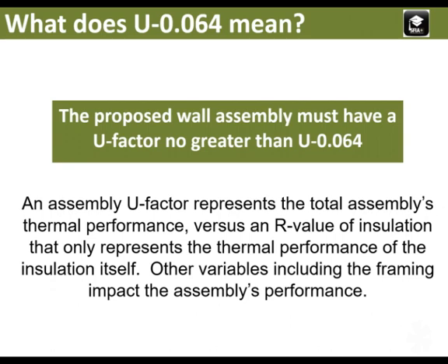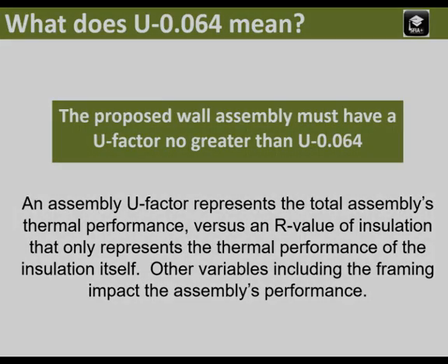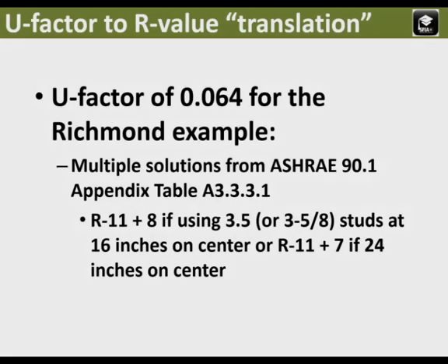Remember that this is different from the R value that only reflects the performance of the insulation versus the entire assembly. One point of clarification here is that you might see or hear someone talking about the effective R value of a wall. If that's the case, they're likely referring to the inverse of the U-factor for the entire assembly. Even though we've talked about U-factors, in reality you typically need to break that down to requirements for specific components that go into the wall.